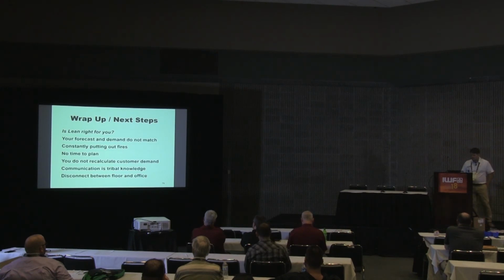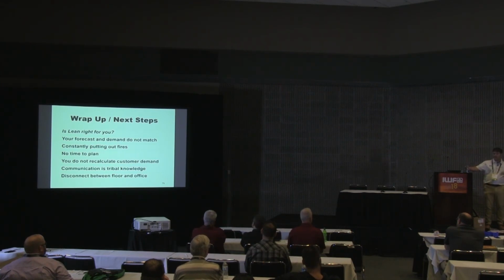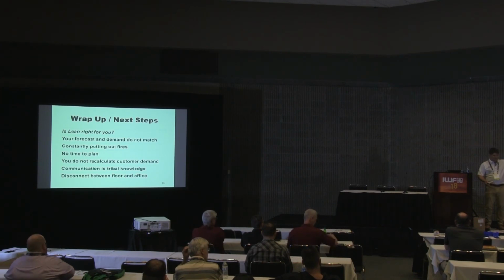Do you not recalculate customer demand? This is one people don't even think about. Customer demand is about takt time. Am I really gauging how fast I need to be performing every day of the week? Or am I just looking at, this is how many we need to make this week, this is how many we need to make this month? Go do it. Well, how do you know if you're on target to meet that? You need to know where you are, because in real life, it goes up and down. Okay, material shortage. Now how do I make that up? Then the firefighting starts.